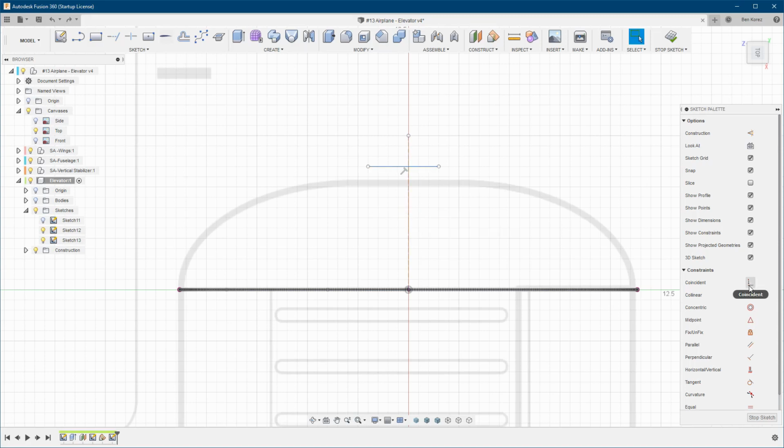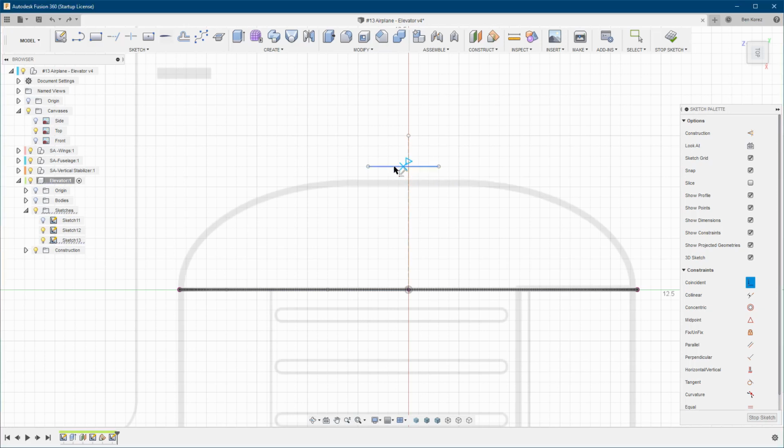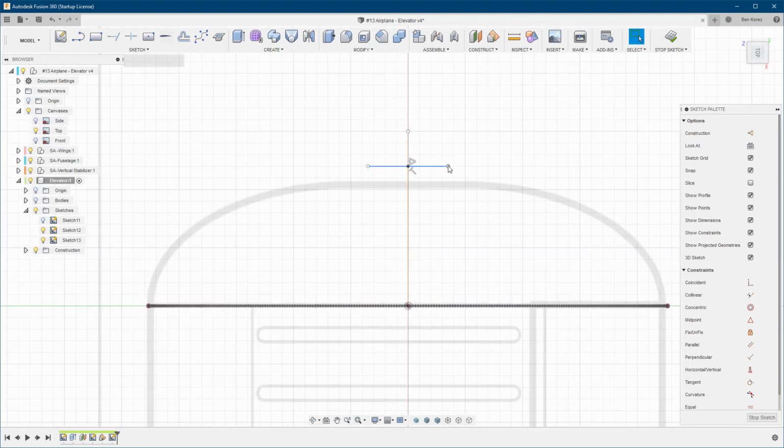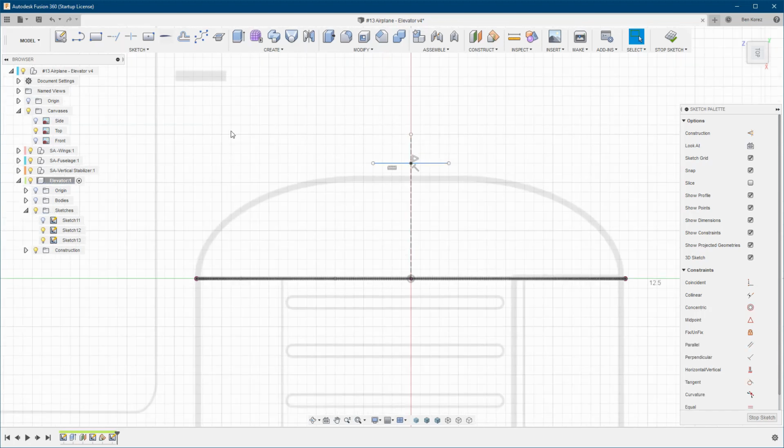not like that. I'm going to create a coincident constraint, and I'm clicking now on the shift command in order to find the center of this line and center it on this line here, on our vertical line here. Good. That means that, you know, we can see it's going to be equal on both sides. So I'm going to need something like that, and we're going to play with it later.